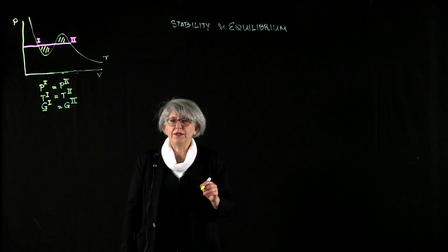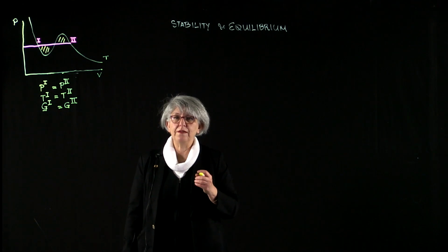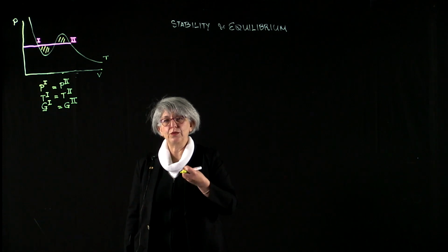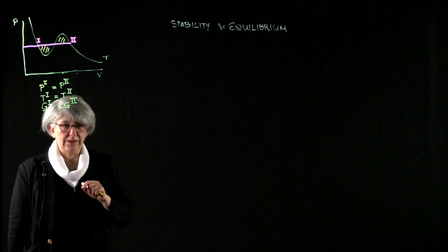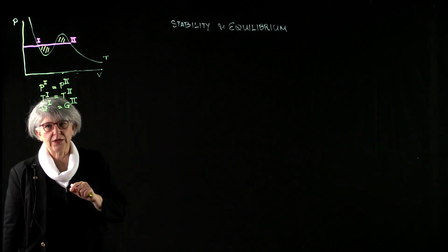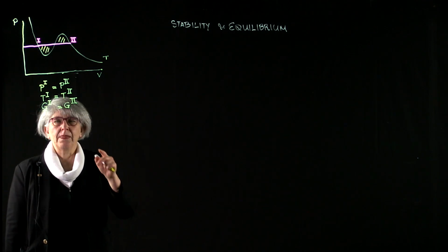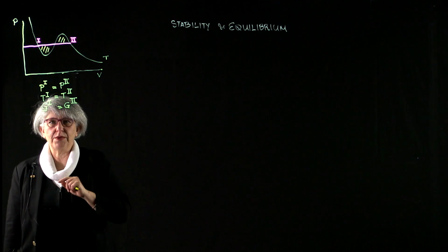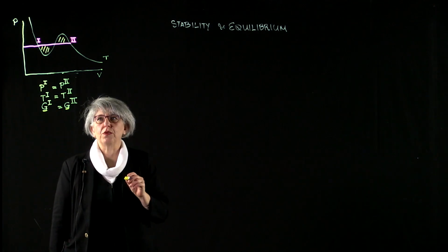Today we are going to establish the equilibrium condition for a domain where we have vapor state and liquid state of a pure component at equilibrium. In the previous video we have established the mathematical identities that led us to the conclusion that for an equilibrium between two different states of aggregation of a pure fluid, the pressures should be equal, their temperatures should be equal, and their molar Gibbs free energies are going to be equal.